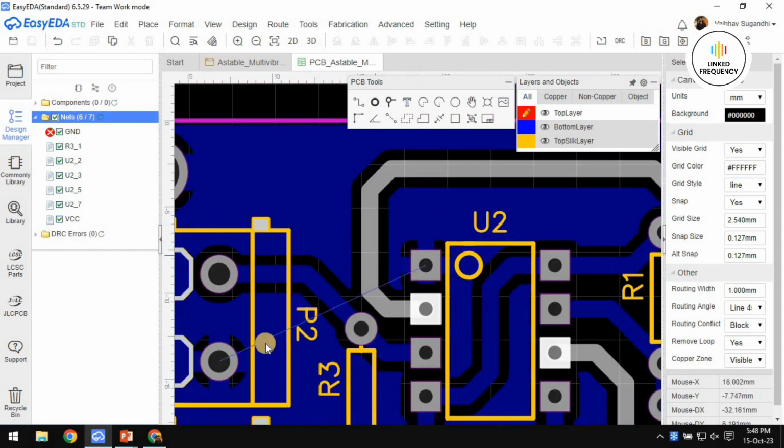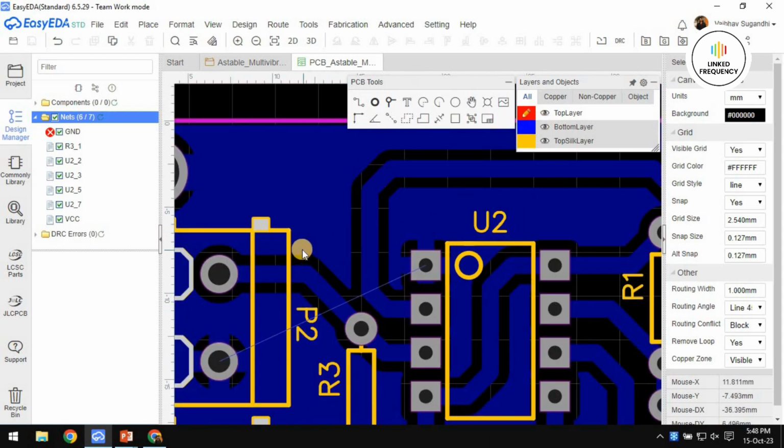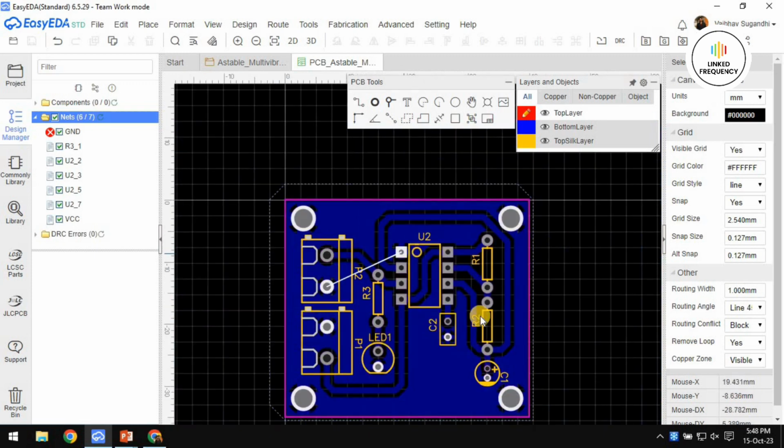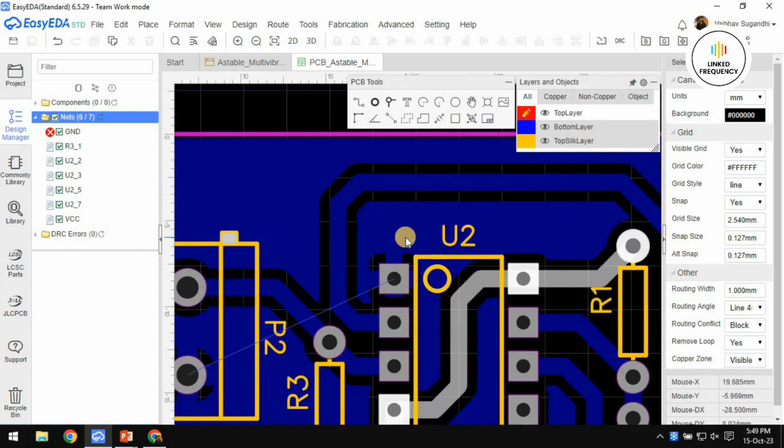In mass production, it is always better to use a copper track by using another layer of copper in the design itself. In the manufacturing, it will be taken care of. But right now, we know that this is a practice project for the PCB designer, and this is very suitable for low-level or low-cost manufacturing, you can say. At that time, what we are going to do is use these pads. Can you see this one? There is a pads option here. You can press the P button on your keyboard as well, which will bring the same option.